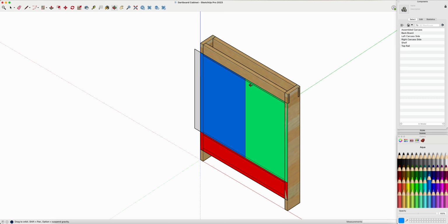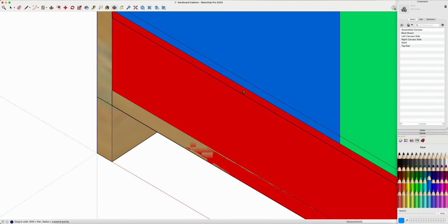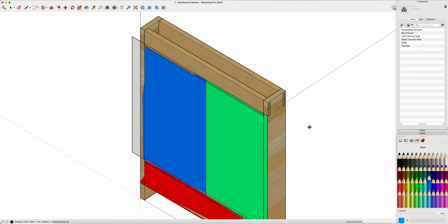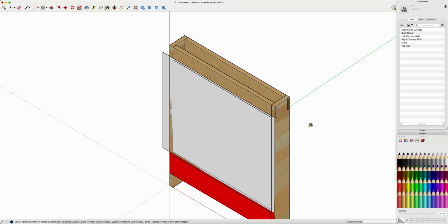We're going to have a right door and a left door, same sizes, half overlay at the top, half overlay at the bottom, full overlay on the two sides. And then our drawer, again, full overlay on the two sides, half overlay at the top, but a full overlay at the bottom. And the reason that we've got these drawers and doors overlaying the joints is if our project is slightly off square, this overlay process enables us to hide that from visual obviousness once the project has been constructed.